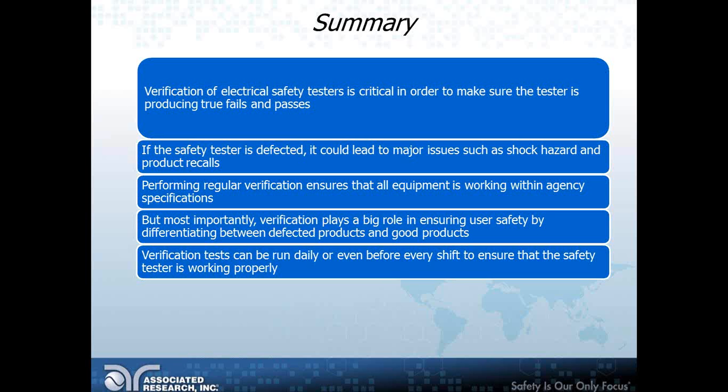Verification methodology gives the operator a simple means of storing the verification test procedure as well as running validations on a daily basis. So here at AS Research, we recommend, and I personally like to, run verification tests on my safety testers in my lab at least once a day before I use them, just to make sure I'm not getting any false passes or fails.